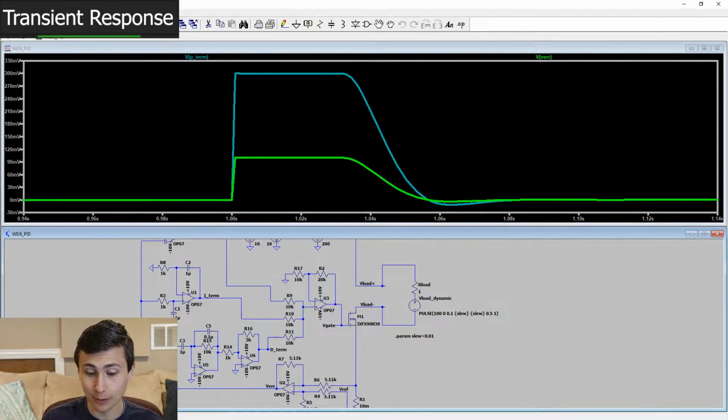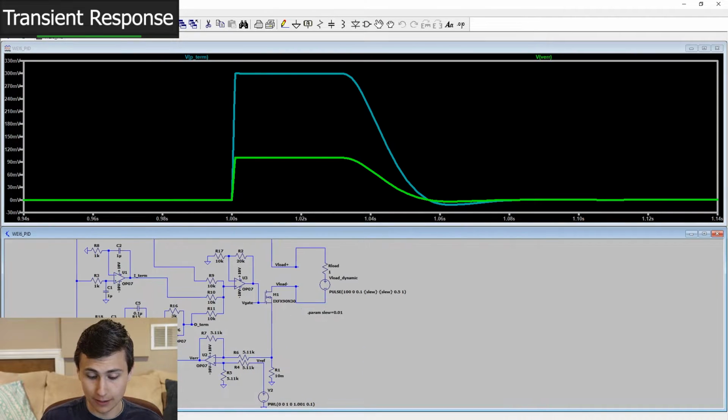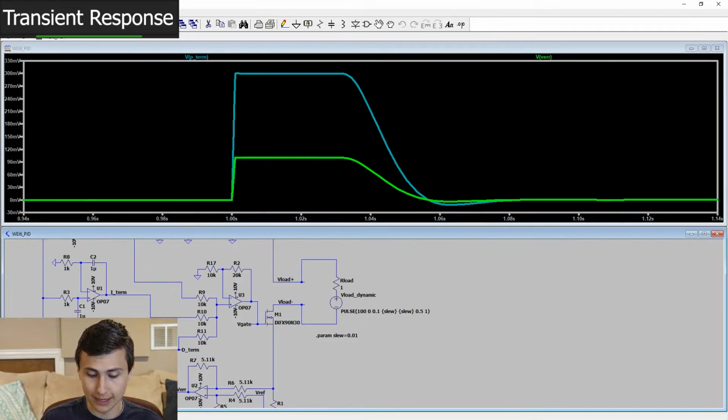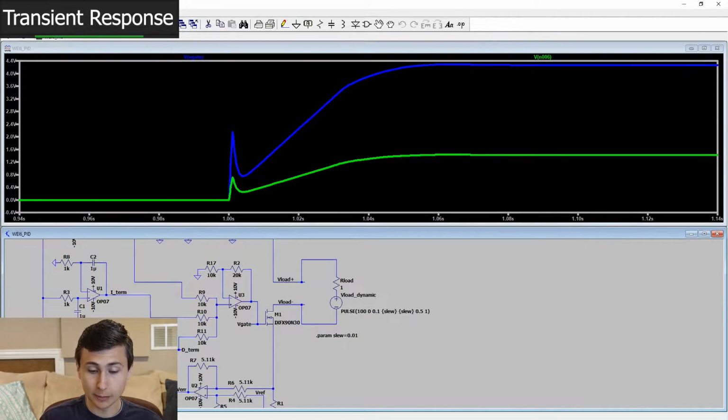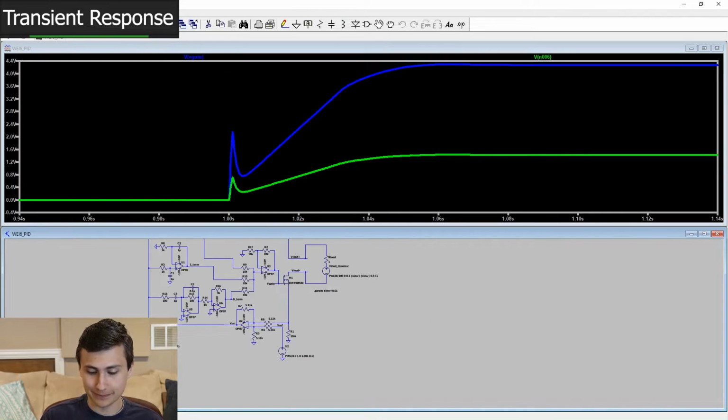Just take a scalar multiple of the error. Pretty fantastic. So the summer takes the input, multiplies that a little bit, and that just makes sure that we don't run out of volts, because 10 volts divided by 3 is not a whole lot. That's not leaving much headroom for the integrator to actually enhance the MOSFET and get us moving.